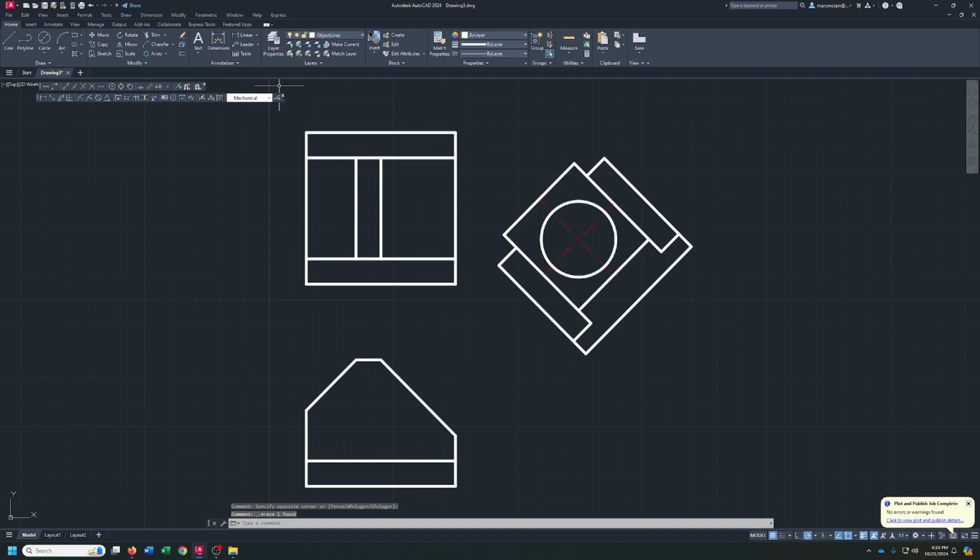All right, so I'm going to go ahead and extend this center line. And I'm just going to come all the way down, make sure it goes to the perpendicular, and I'm going to come up here. And then I'm going to bring one right down the middle. Now I'm going to trim this off, and I can erase these two. All right, so now there's my center line.